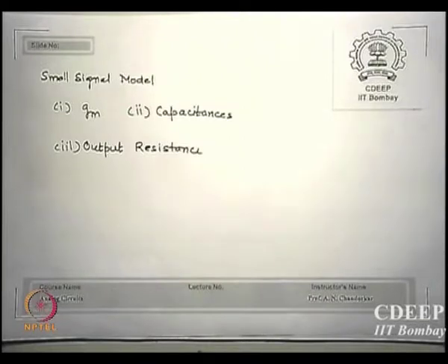we will be able to get the gain, GM and R0, that is the gain part we can get, and also from GM and capacitance we will be able to get the bandwidths. So once we get the equivalent circuit correctly, we will be able to get all the physical parameters known, then circuit parameters can always be evaluated. And if circuit parameters are evaluated, the actual system performance, gain and bandwidth, can also always be found out. So that is the general technique which we will follow. So there is nothing much to say on that.